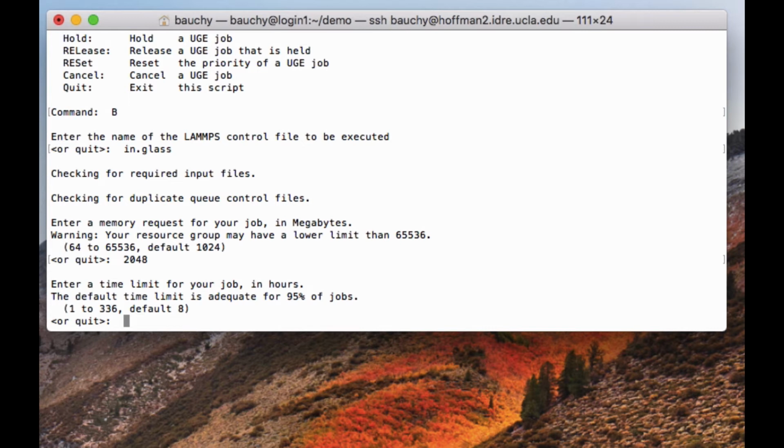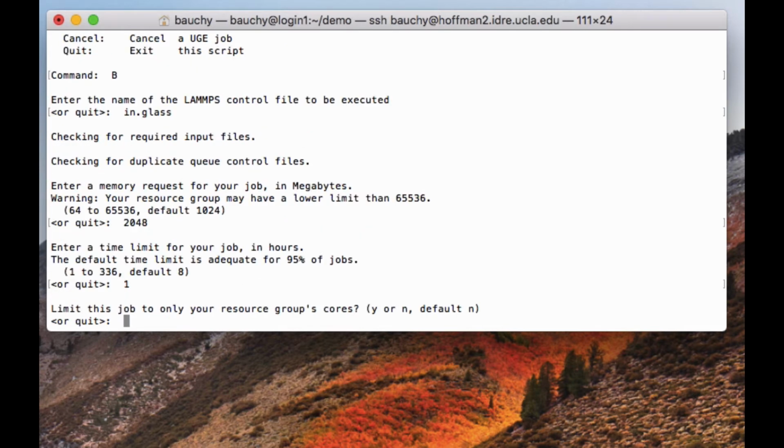So for example, you will probably lose some files if you do that, because the simulation would not have reached the end. So the final data file would not have been written. So here we will just ask for a simulation of 1 hour, which would not be enough for this simulation, but we'll just take this example of 1 hour so that the simulation can start fast enough.